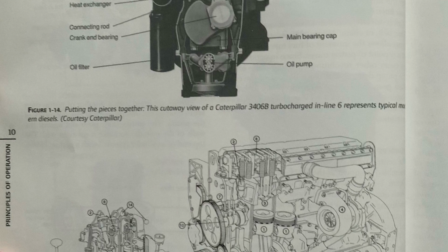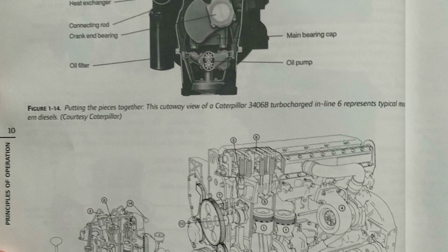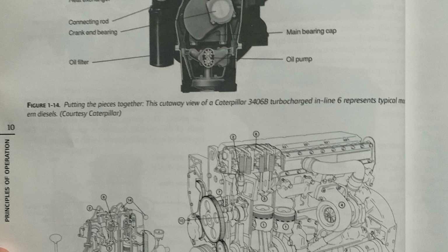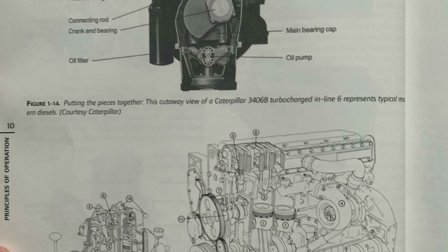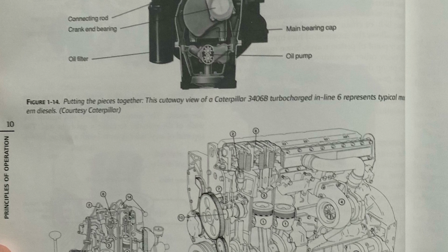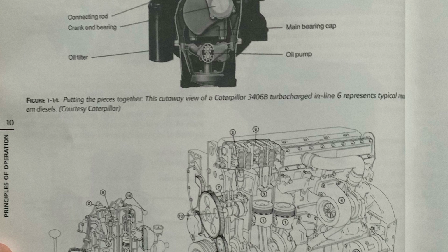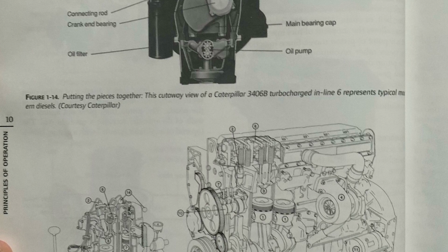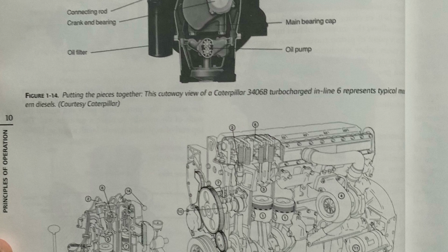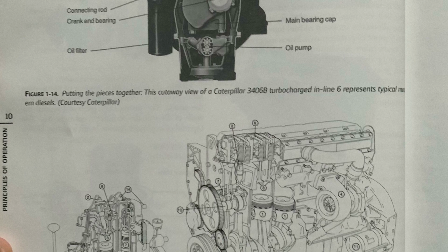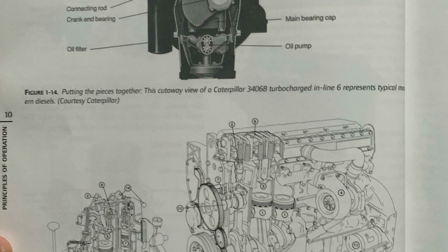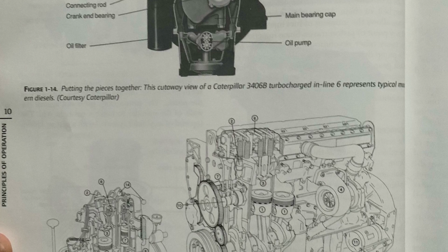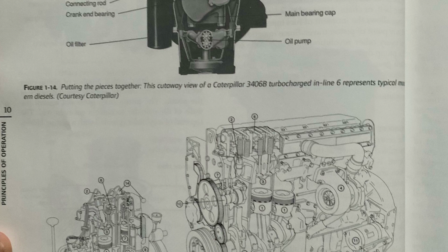The top end of the cylinder is sealed with a casting known as a cylinder head, which contains the injectors, valves, and frequently combustion chambers, water passages, and so on. The valves are set in guides, which are replaceable sleeves pressed into the cylinder head. When an engine begins to show appreciable wear, these valve guides can be pressed out and replaced.